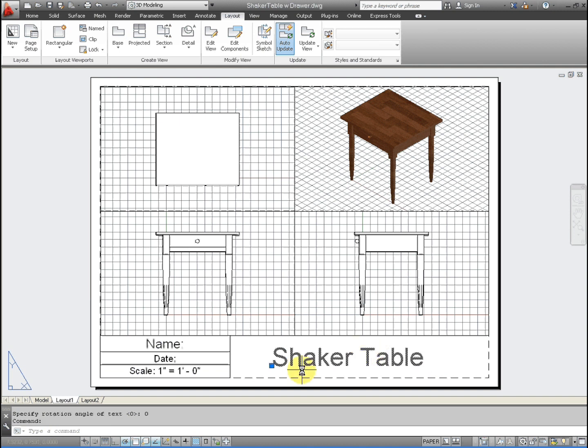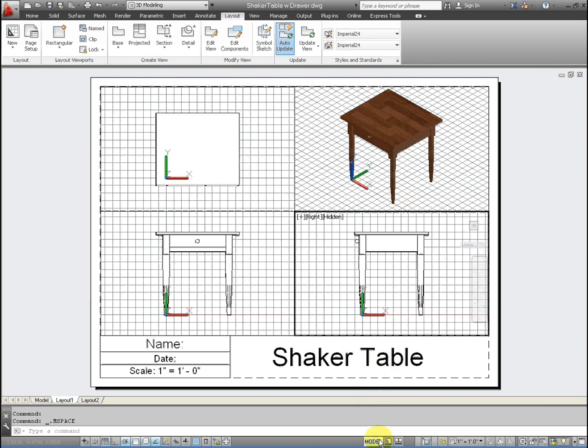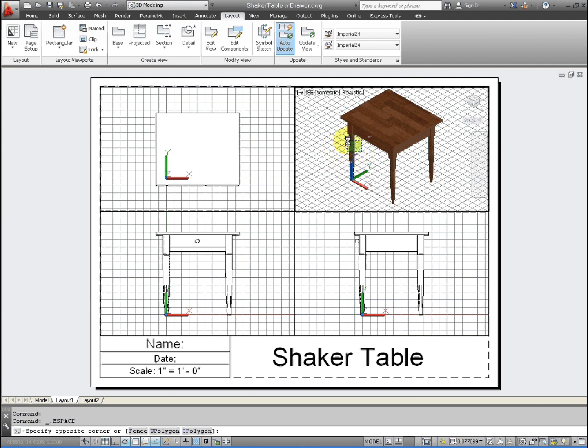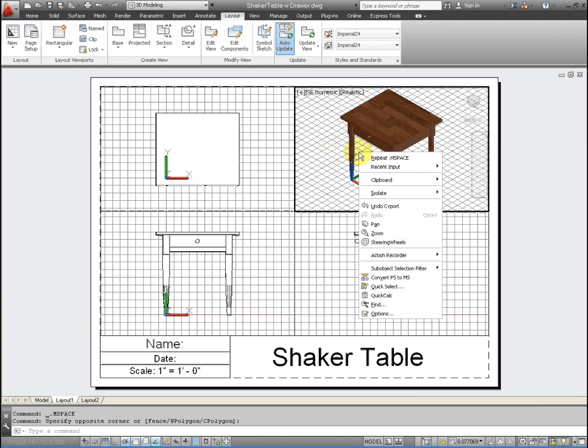If you need to move it because it's too small or whatever, once you select it on the bottom left, there's a little blue icon. You can drag it around. So we're in the paper mode from the bottom, so that means that whatever we do is not going to affect the model. But if you, for example, want to have a different view, click the model icon below, and you can go in the orbit. So if I would delete the leg here, for example, it would delete, but we don't want to do that, obviously.